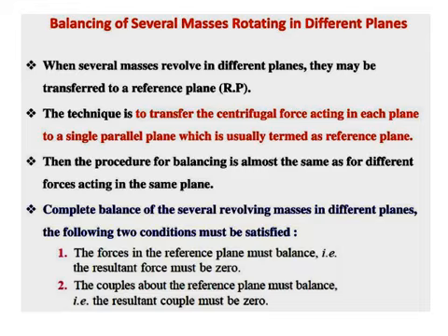In this slide, the balancing of several masses rotating in different planes. The several masses are placed in different planes. We consider one of the planes as a reference plane. This technique transfers the centrifugal force acting in each plane to a single parallel plane. The procedure of this balancing is almost the same as for different forces acting in the same plane.